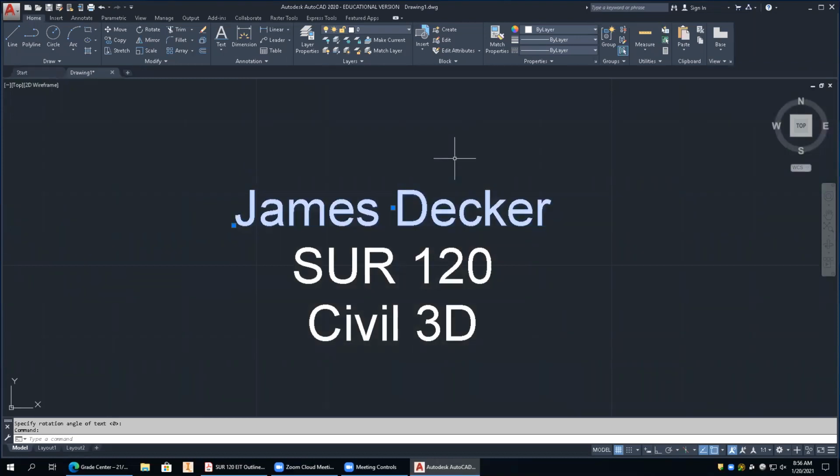So this will snap to a text justification point. So if you have a piece of text and you want to align something underneath it, you can snap a line to that point using insert and then bring the line down. Again, it's a little bit easier to use with single line text than with multiple line text. Okay. All right, any questions so far?